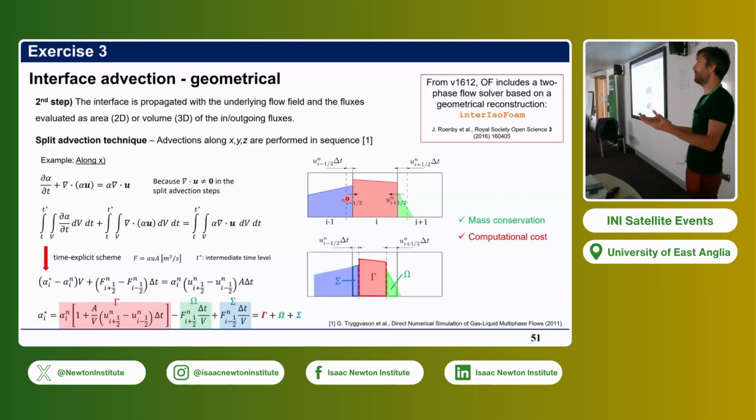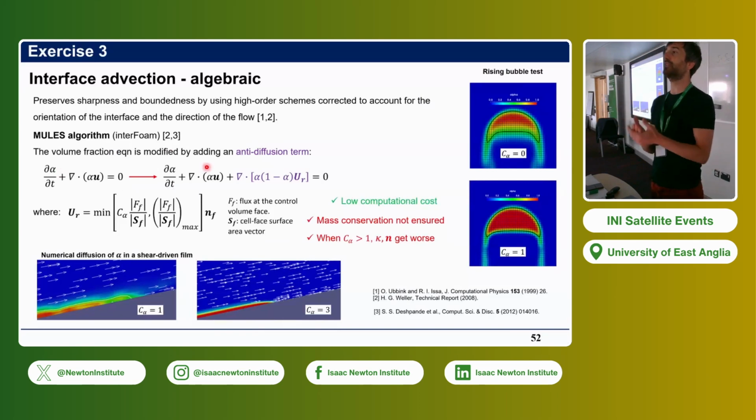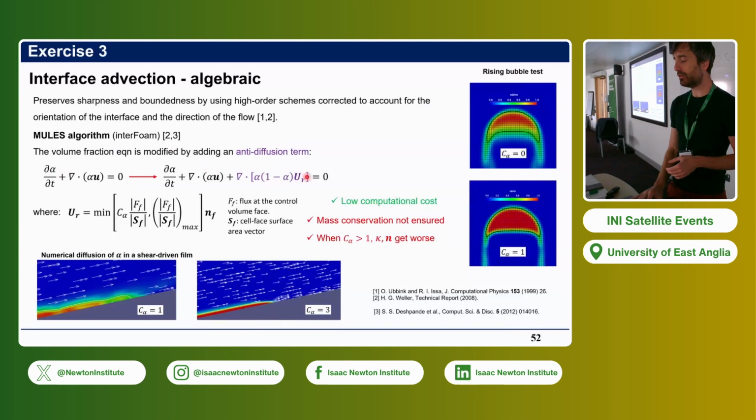But remember that OpenFOAM is designed to be used by industries, so it is done to work with any kind of mesh architecture. So they had to do something. The first VOF implemented in OpenFOAM was algebraic. It uses the typical interpolations on a phase center, so it doesn't use any geometrical reconstruction. But then it uses this anti-diffusion term here.